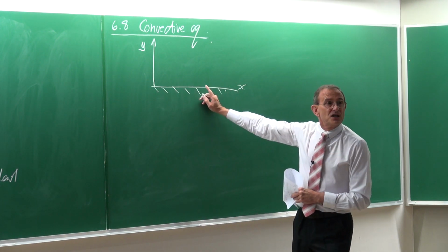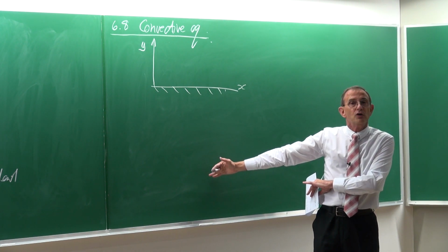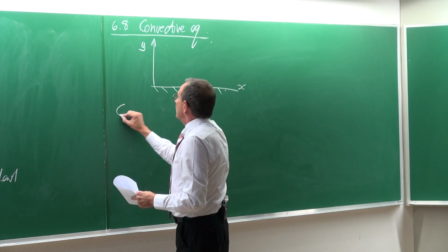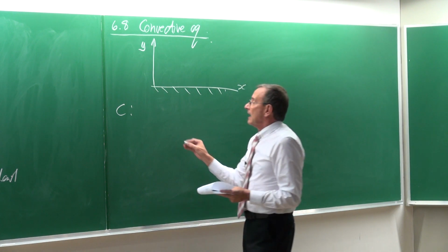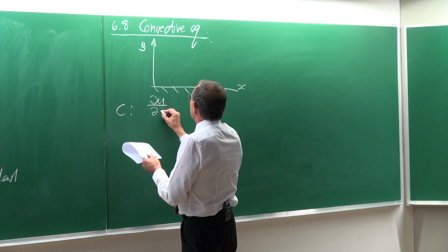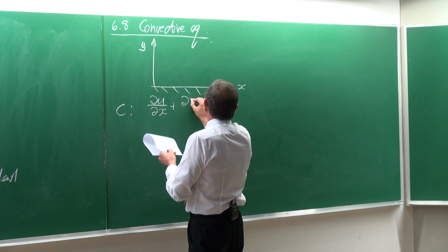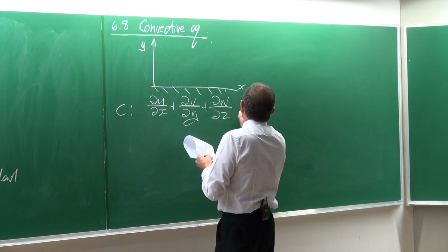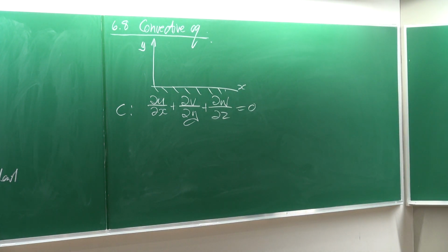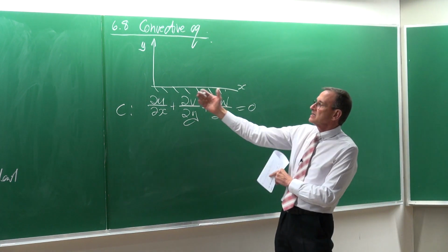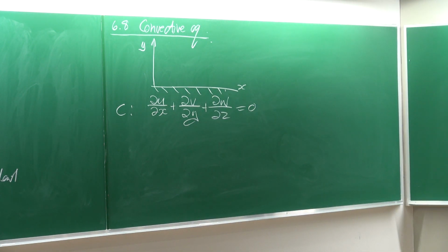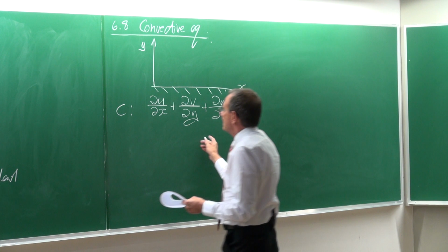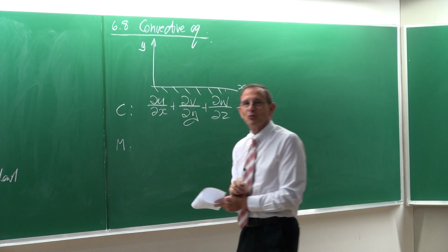Right. Now, if we consider this problem, and I'm not going to look at all the terms one by one, I just want to give you a little bit of background. Then we're going to look at the continuity equation, and the continuity equation can then be written as partial du/dx plus partial dv/dy plus partial dw/dz is equal to 0. And of course, there will already be an assumption here in the sense that it is for constant density, so it's incompressible flow. So there are many assumptions that are being made in these equations.